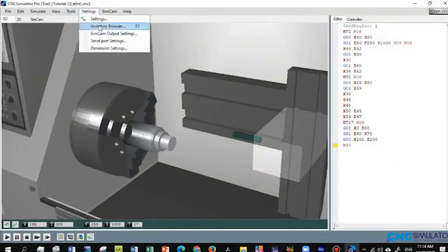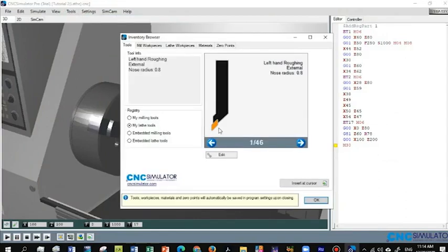As you can see here, you can select the cutting tool, for example, left hand roughing. You can select a lot of different tools here, left hand finishing, left hand triangular straight stream, and so on. So you can select which of the lathe tools need to be used here. Just keep it for the one that we have before.